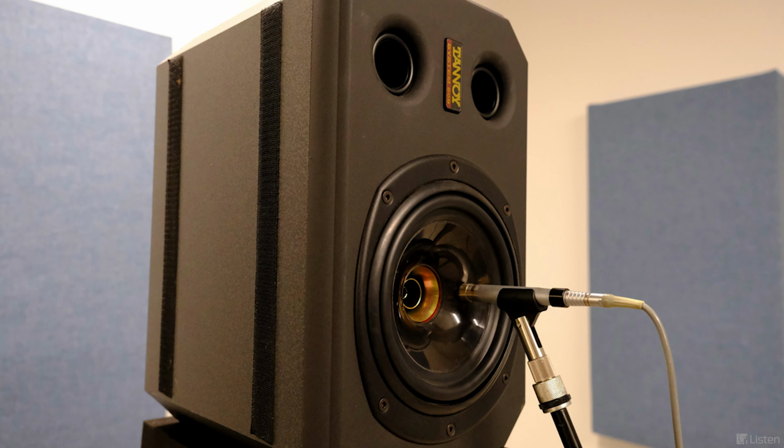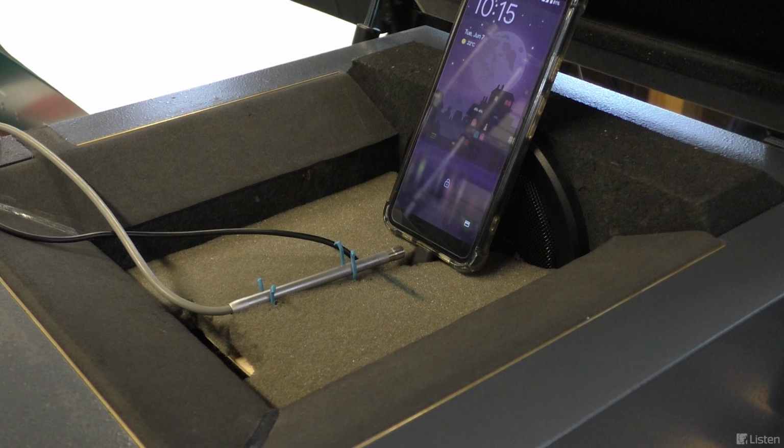I usually make these measurements in the near field to reduce background noise by placing the microphone close to the loudspeaker. This is particularly useful for the many modern devices that feature DSP that treats pure tones as noise and tries to filter them out.